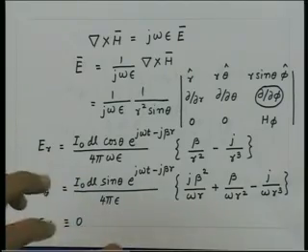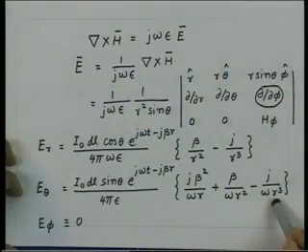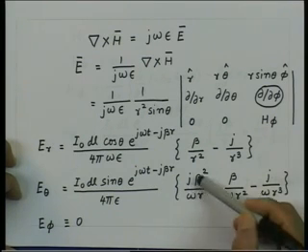on the ends of the current dipole you have accumulation of charges. So, we have essentially a bundle of charges which are sitting at the ends of the Hertz dipole. As the current oscillates, these charges also oscillate. So, you are having a dipole, and because of that dipole you get the electrostatic field, and that is given by this term. So, its variation is 1 over r cube,